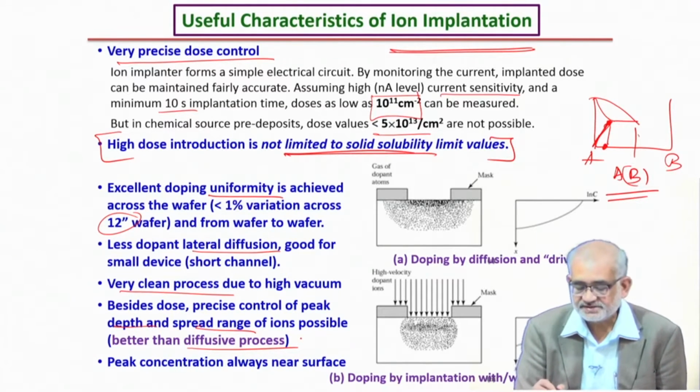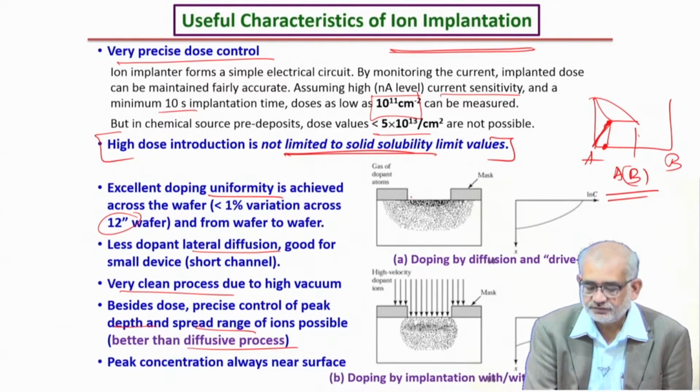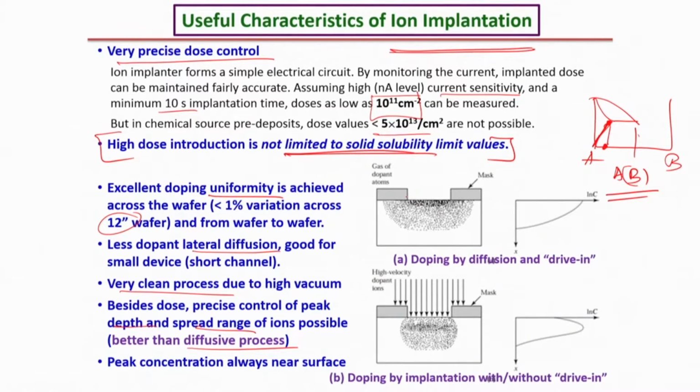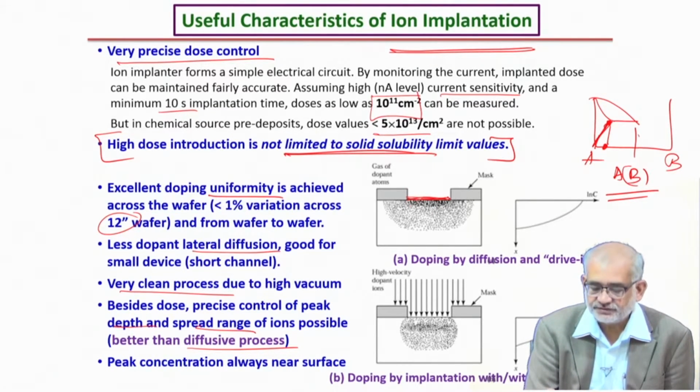Now, what it means is that in a typically thermally activated process, say for example, if you electroplate or deposit by vapor deposition this amount of dopant, and even if you have masks here, when you allow diffusion to take place, diffusion occurs certainly down below, but also laterally.